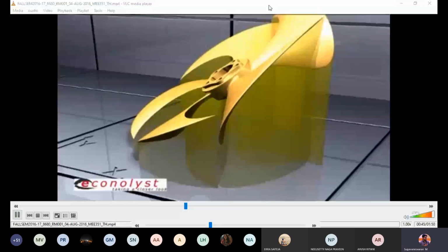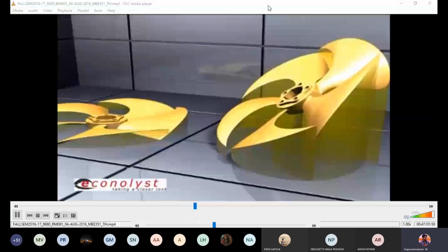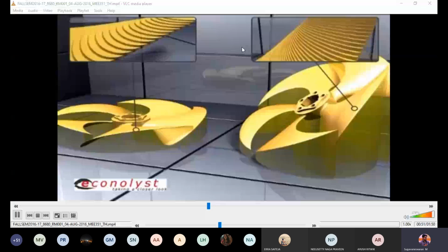In addition to the amount of support structure needed, part orientation will also affect the surface roughness of the part and the time it takes to build that part. So if you look, I have shown here two orientations. Let us say this is the first orientation and this is the second orientation. According to the first orientation, this is the support structure I require. And according to the second orientation, the support structure required is shown in the gray, light yellow region.